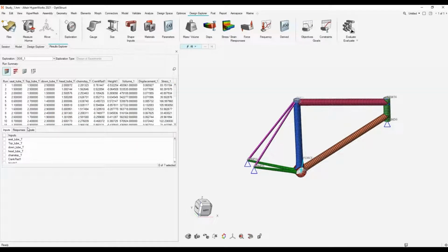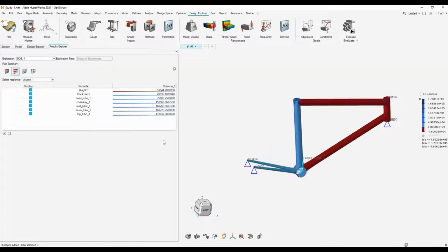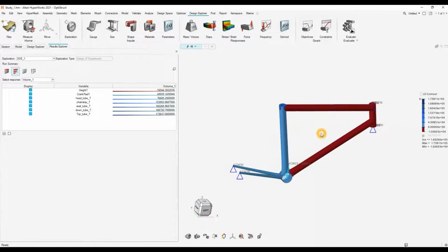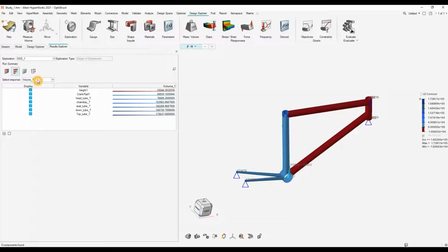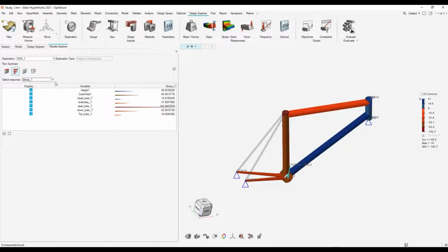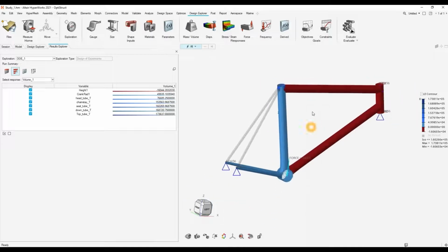Now we can also start looking at the linear effects between your data. So to actually really understand your data, you can see just how your inputs would affect your outputs. You can look at the relationships between them, whether they're positively correlated or negatively correlated. You can see at this point, say if we were to increase the thicknesses of your different tubes, this in turn would obviously increase your volume. And from there you can see it with the positive contour and the colouring of your plots too.